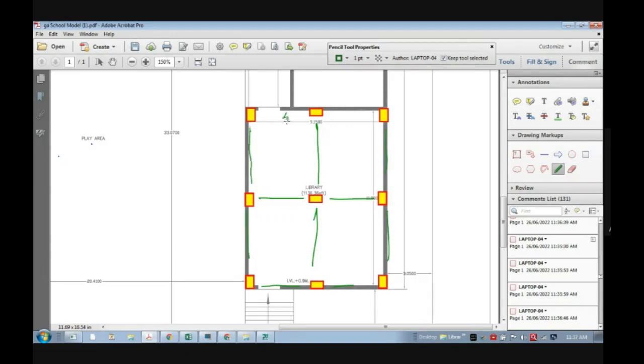The span of the slab will be 4.5 meter, and this one is 6 meters something, and I will have a 2-way slab, and it's a very easy problem now from a structural point of view. So this is one case, where you do this by keeping this one column inside the room. Now let's say the architect is saying that I don't want this column. So let's say you have given this solution to him and he's disagreeing with this. He's saying, no, I don't want this column. Now let's go back.